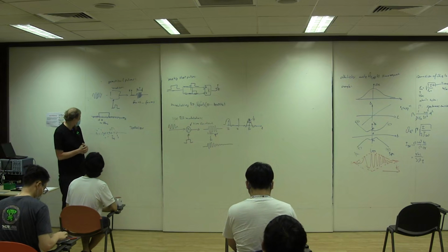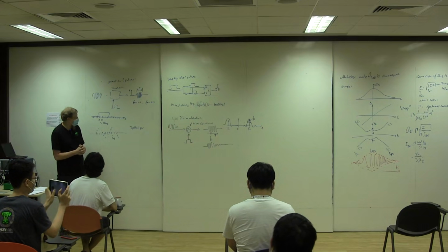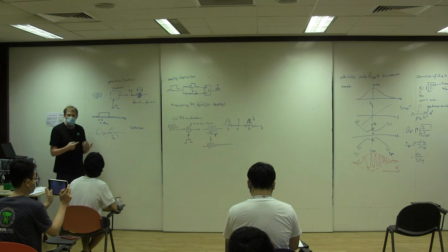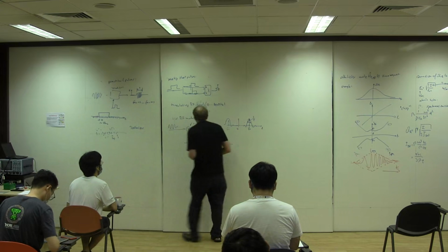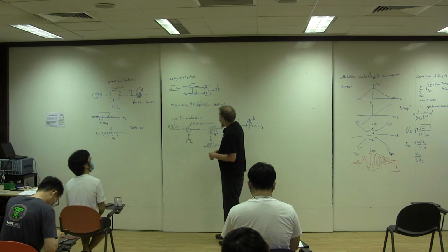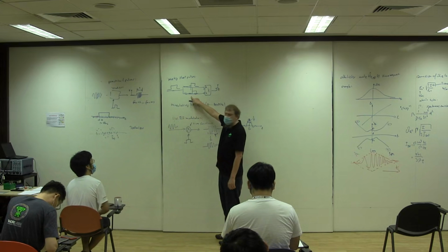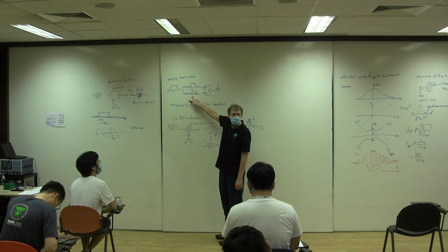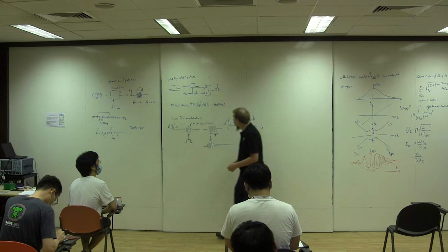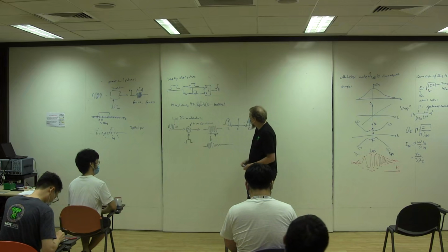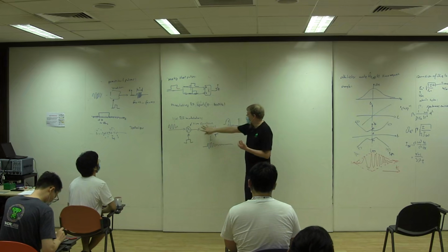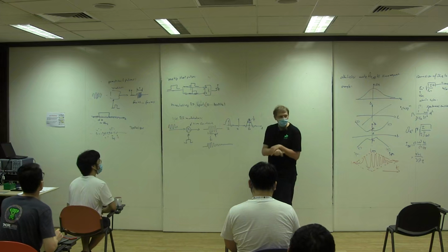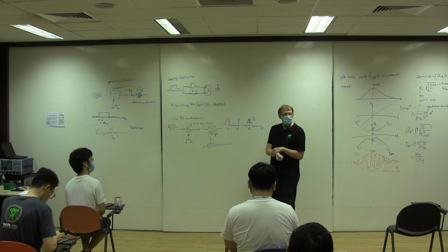I mentioned that the typical way of making wavefronts is to generate the envelope and multiply it with a modulator or mixer. If your envelope generator is too slow, play with tricks like that, and that typically works. One thing I should say is that I pretend the pulses that come out here have the right amplitude to be digested by your modulator. That's typically not the case.